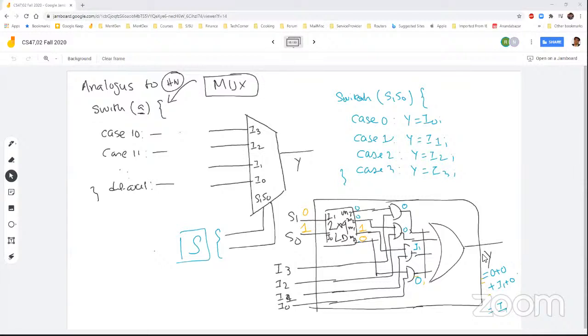Okay, 4-bit information. So what if I have a multiplexer? Let's mark the inputs I3, I2, I1, and I0, selection bits 0 and 1, and output Y. Now the twist here is that these are not single-bit inputs. Let's say these are 4-bit inputs. So each of these bars is actually representing a 4-bit value, right?